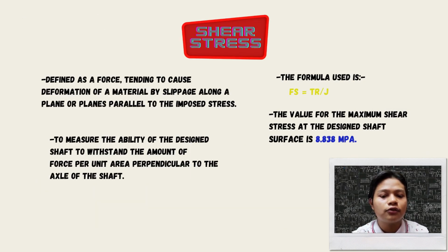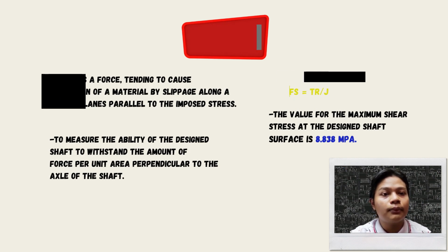Next is shear stress. Shear stress is defined as a force tending to cause deformation of the material by slippage along a plane of the object. We calculate the stress as shown in the slide. So the value we get for the stress for the shaft is 8.838 megapascal.